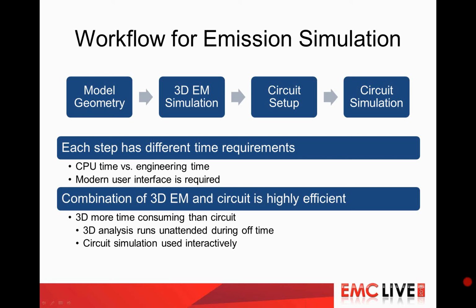The time domain method is typically more efficient for very high geometric complexities, so you can use it for even highly complex PCBs, even for multiple PCBs in one model. On the other hand, it's, for example, not efficient for low frequencies. The frequency domain method is, on the other side, efficient for low frequency results, while it slows down or becomes impossible for very complex geometries. But we're talking really, for example, of 2 or 3 PCBs inside the housing. So that's what I call a complex geometry.